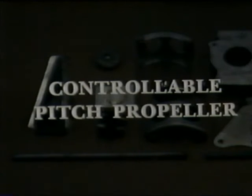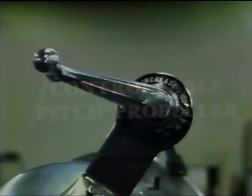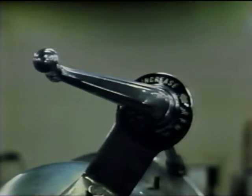A controllable pitch propeller is designed so that the pilot can select any blade angle within the propeller's range at any time during the aircraft's operation. The controllable propeller is operated from the cockpit by a crank handle mounted on the instrument panel.